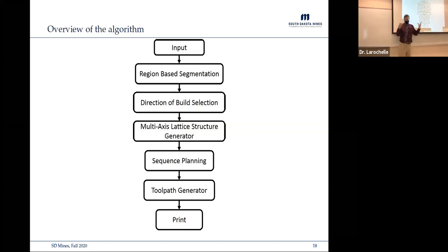If I take a complex geometry and break it up into a bunch of little pieces, there are probably multiple ways that we can make the little subregions to yield the final part, and then we need to ask ourselves, are they all feasible? So we actually explore the geometry to figure out what sequence I want to build these individual segmentations in to yield the final part, and not get the robot tangled up as a pretzel, or have subparts collapse and fall or fail during the build.